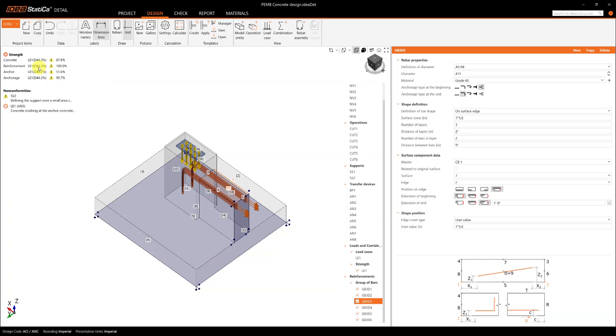The analysis stopped at 44.2% of the applied loads. So this means something of these 4 items failed. In this case, the reinforcement failed, and also the anchorage was close to 100% of utilization. Here, you will see why it fails. So it's telling you something. Concrete crushing at the anchor concrete interface due to the shear has reached the limit. So this tells you something.